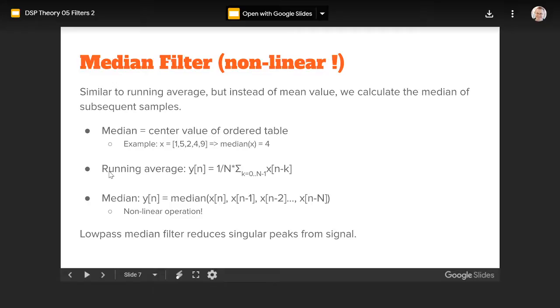Wrong values, missing bits from the end, or missing bits from the beginning, or totally bogus, or a couple of values like 0xFFFF. That's usually bogus. Let's see, 0xA5, 0x5A. Anything that has A5s, that's usually also bogus.